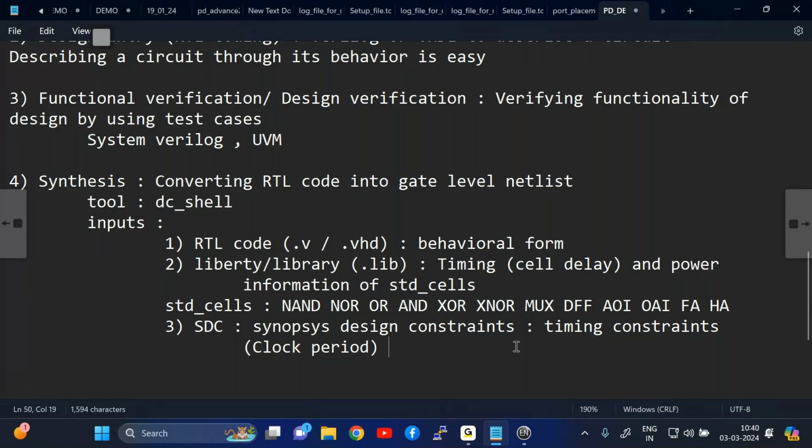In real synthesis, they implement various strategies and techniques to meet the clock timing and to meet the power. Synthesis is not one day or one week of work, it's one month of work. Converting a bigger design into a gate level netlist is not 1 or 2 days of work, it's like 1.5 months or 2 months. They have different strategies for converting RTL to gate level.